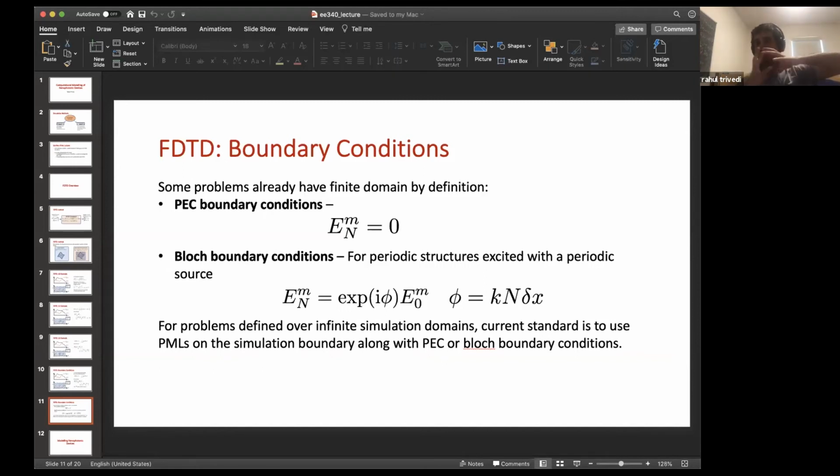Now imagine your device is radiating some power that's hitting this perfect mirror, and it's going to reflect all of this power, right? All of the power that your device radiates is going to be reflected by a PEC mirror, no matter how far it is. If there is no absorption, no matter how far it is, it's going to get reflected and interact with your device again. So you're going to get an inaccurate simulation, because even though your fields are very small at the PEC mirror, when they're reflected, they're going to come back and create significant fields on your device.